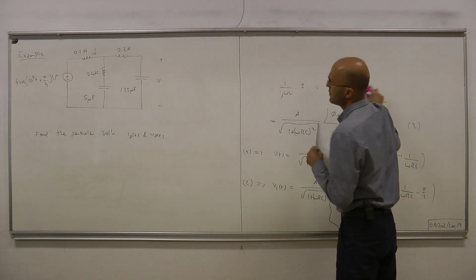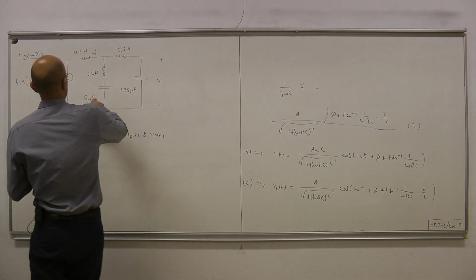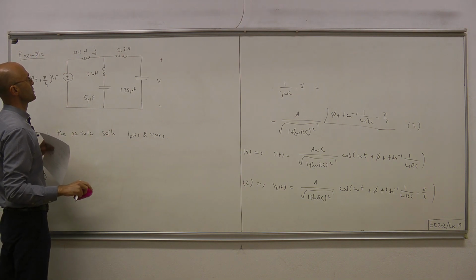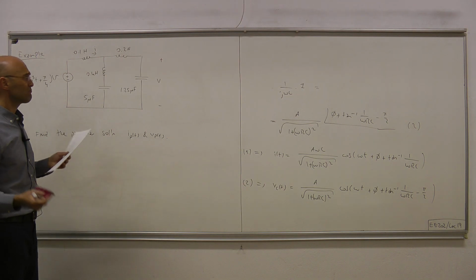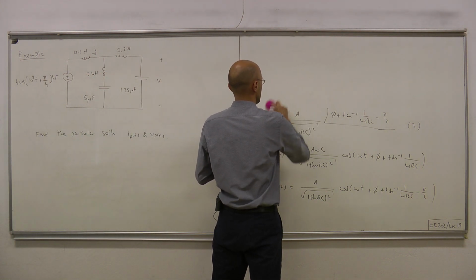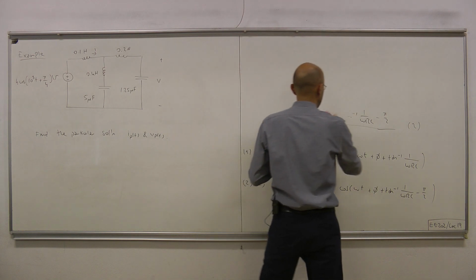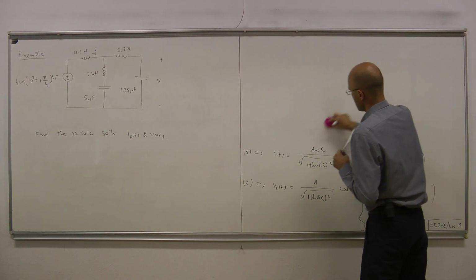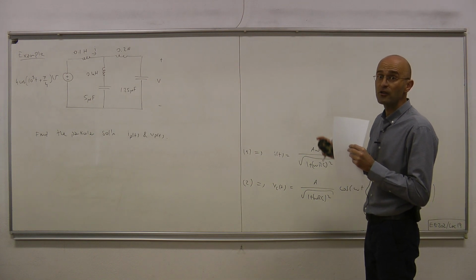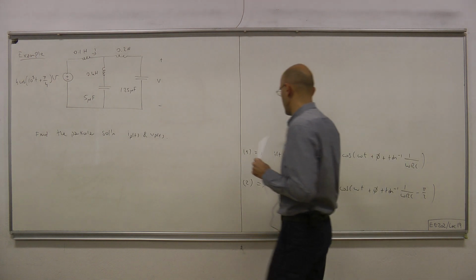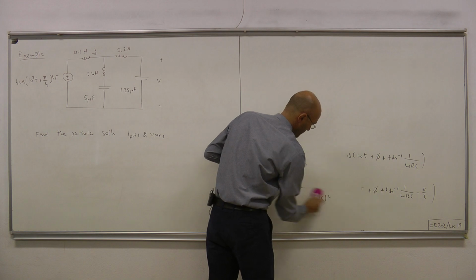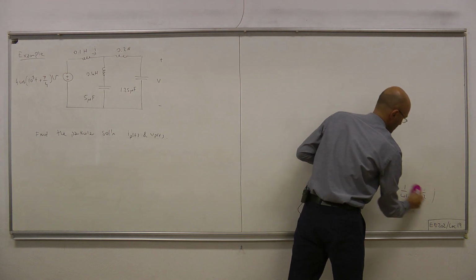Note that this time domain circuit is of order, well, we have 5 dynamic components, but the order seems to be 4. In any case, it's not a simple circuit, but thanks to phasor domain analysis techniques that we have just developed, this just becomes a circuit of degree 0 in phasor domain because it's an LTI resistive circuit in its phasor representation.